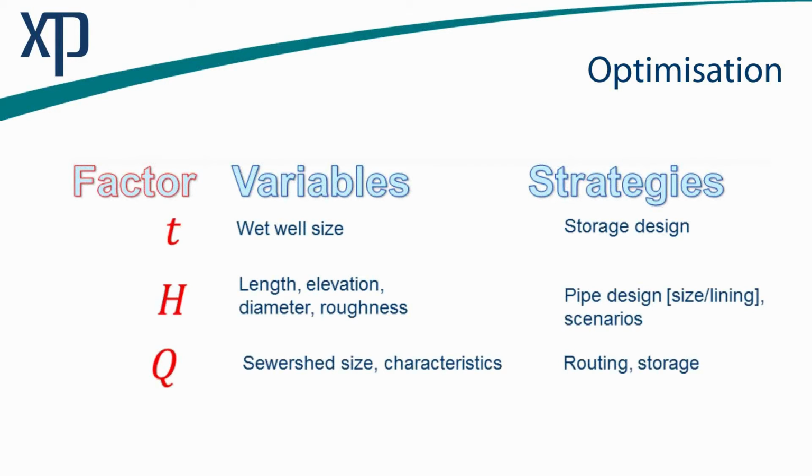And the most important parameter, of course, is, well, how big is the catchment? What are those characteristics we get from those growth factors we spoke about earlier? And then we get to route those, move those across the entire network. In a municipal scale model, we get to assess pump performance from point A to point B, all the way through to the treatment plant.